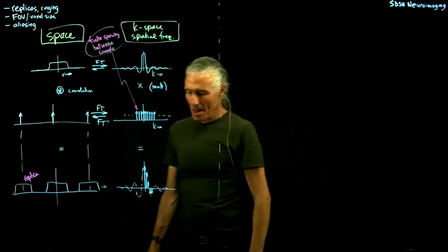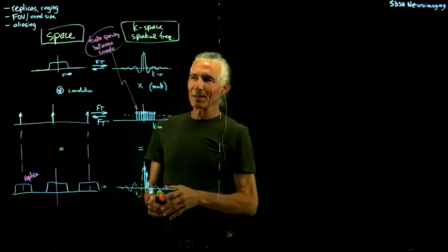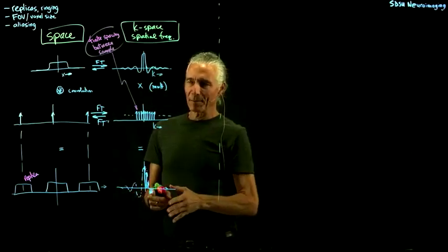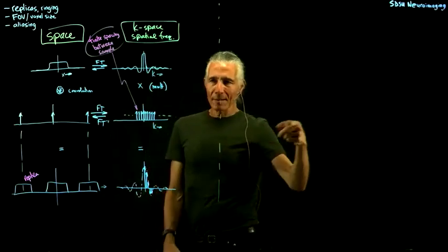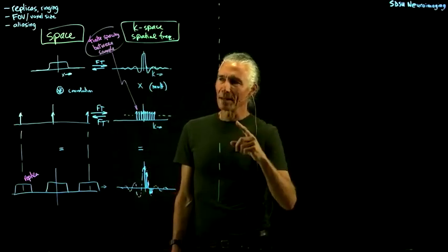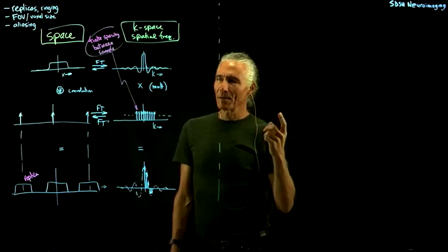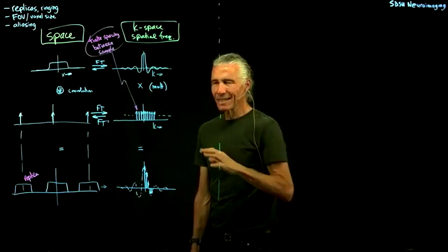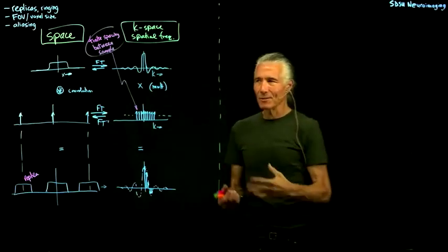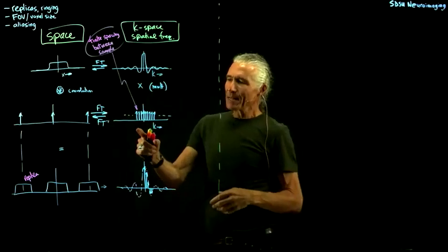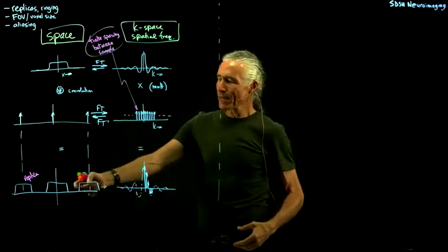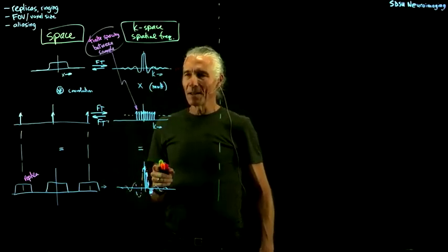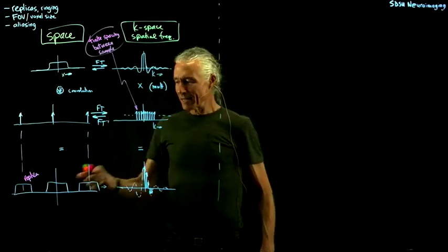So this is kind of counterintuitive. We talked about the effect of finite spacing between samples if you're sampling a time signal. If you have a time signal and you finitely sample it, there are various problems that can arise if you don't sample it fast enough. That's, for me, the intuitive entrance into this idea of finite sampling. This is sort of the inverse of that. Instead of finitely sampling on the time or space side, you're finitely sampling on the spatial frequency side. But it has the same effect.